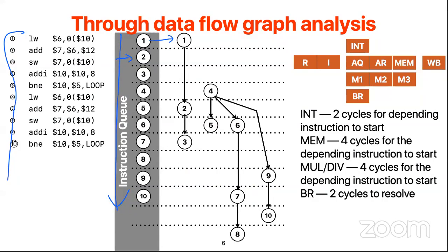However, in the second cycle, the second instruction needs to wait for the outcome from the first instruction, and because the first instruction takes 4 cycles to get its result broadcasted to the second instruction, we put an arrow here that is 4 cycles away from the first instruction. And the third instruction, if you look at the dependency, still depends on the output of the second instruction.